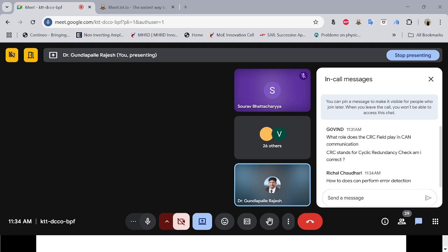So with maximum bit stuffing, at the worst case, the frame with 0 bytes of data will be 55 bits, whereas with an 8-byte data field it will be 135. The average bit stuffing will give 49 bits with minimum data bytes, whereas with the maximum data bytes it will be 114 bits.